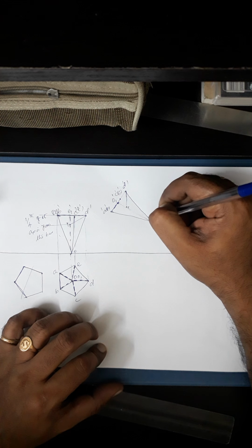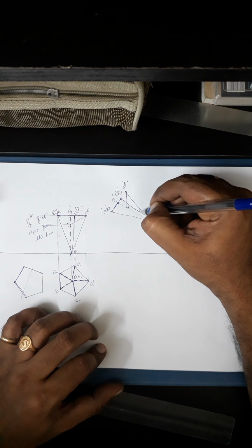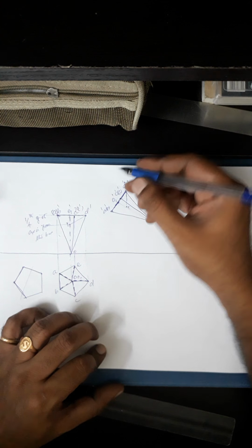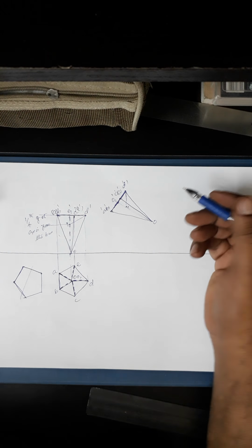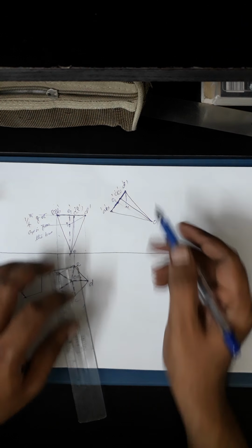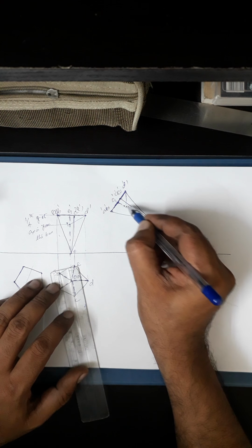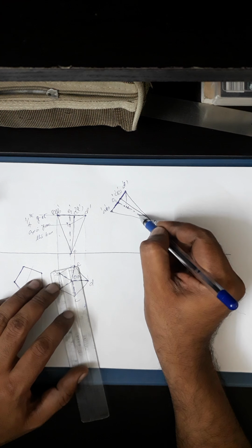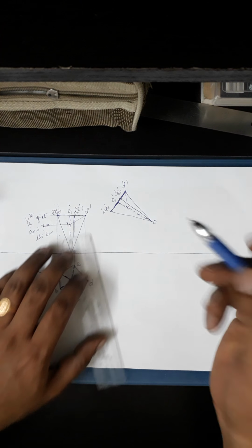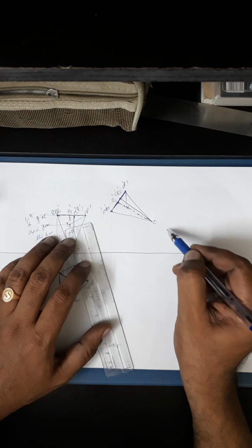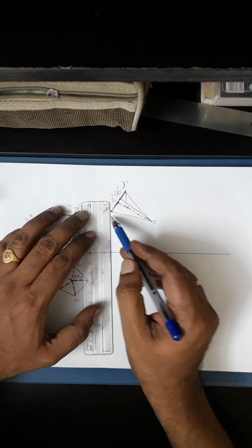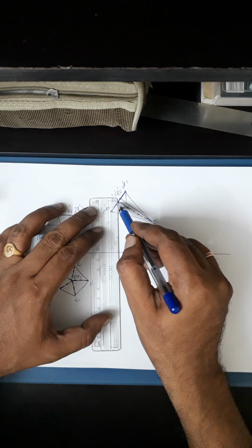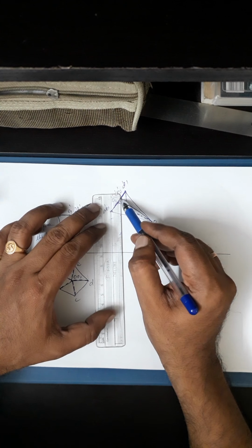So get your view, the same view which is drawn over there. Now this is the view which is redrawn. So O1. In this position you can observe that this axis is inclined with HV, right? So this is inclined with this much angle with HV. Then what will be the axis length on the top view?